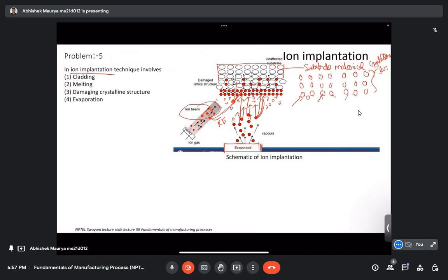So likewise, a few layers of the surface atoms of the substrate material get distorted. Earlier they were in very good crystalline form, but later, some will go there, so they will become a kind of amorphous, and their crystallinity goes away because of collision of ions, as well as this material which needs to be deposited, with the substrate material.